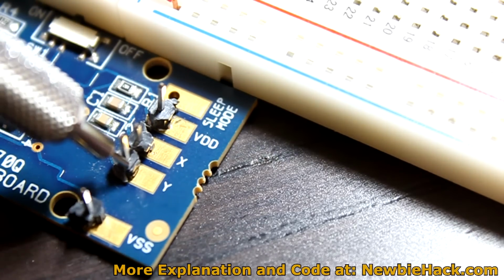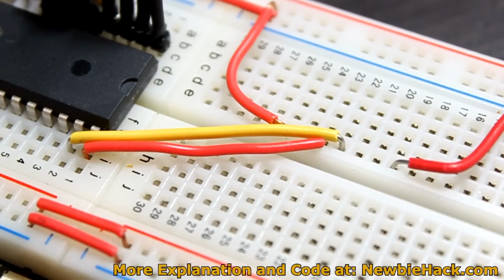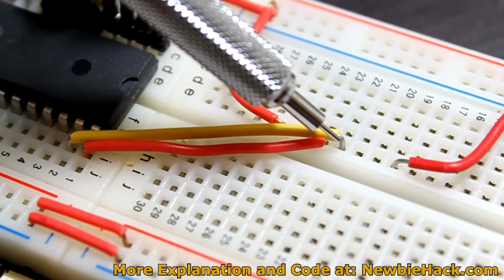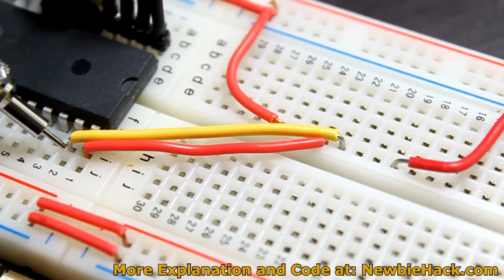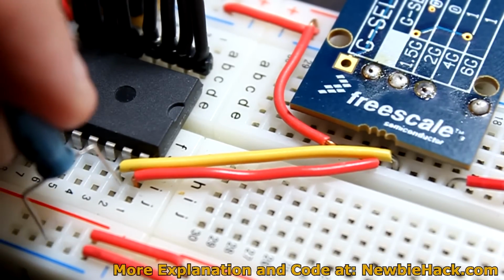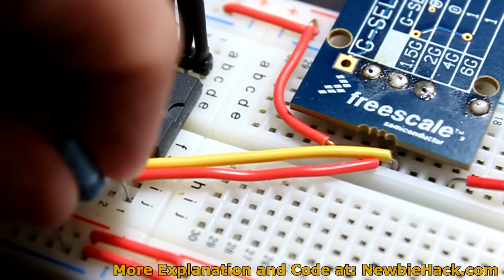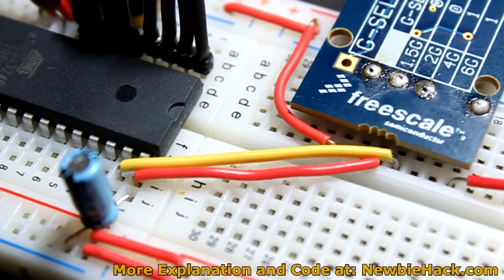I put another pin here, and on the breadboard, I'm connecting X to ADC 0 and Y, which is the next pin over, to ADC 1. To smooth the signal a little bit, we're going to be using the 10 microfarad capacitors as we did in the previous videos with the accelerometer on both of the channels.